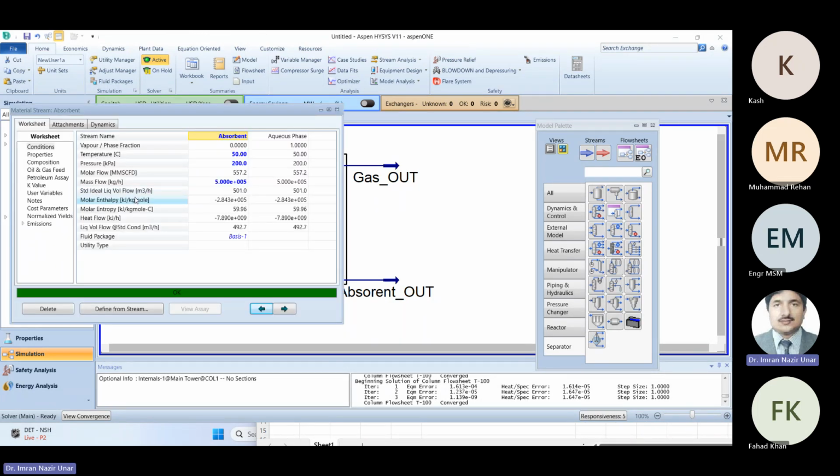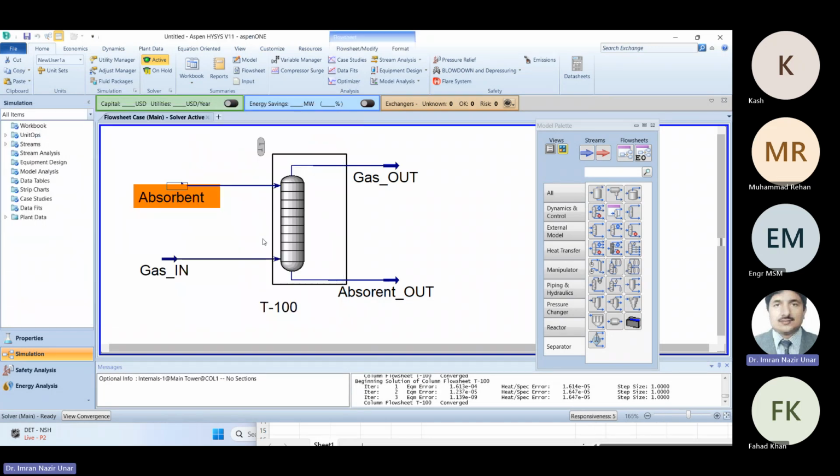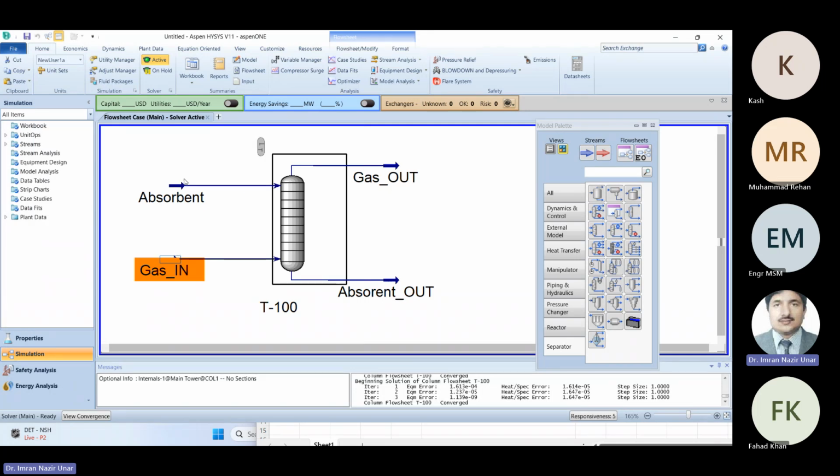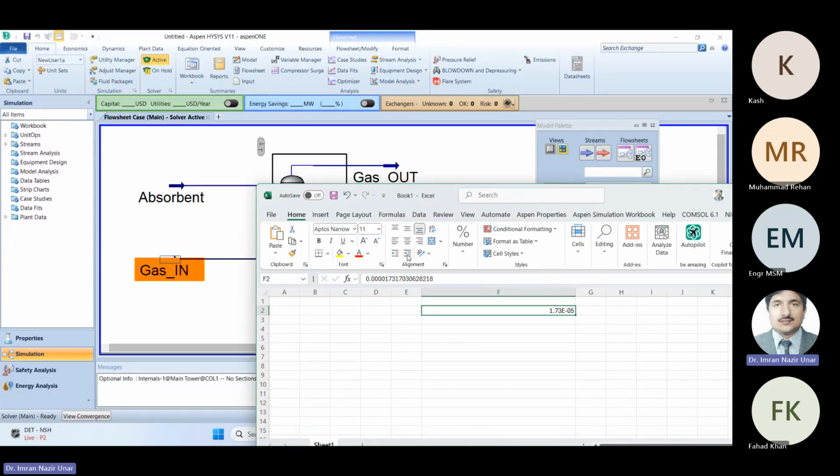Now see, we have increased water almost 500,000 kilogram per hour. This is a huge amount. Now, complete CO2 is being absorbed, which is in gas form, a total of 15% of 100 kilogram, which is actually 15 kilogram. Now, if 15 kilogram is being injected into 500,000 kilogram, what's the percentage you may find in this portion? The percentage is very low in this total quantity.